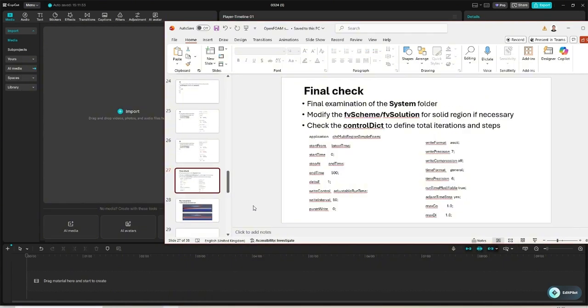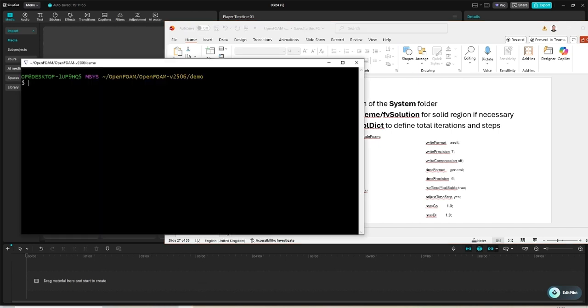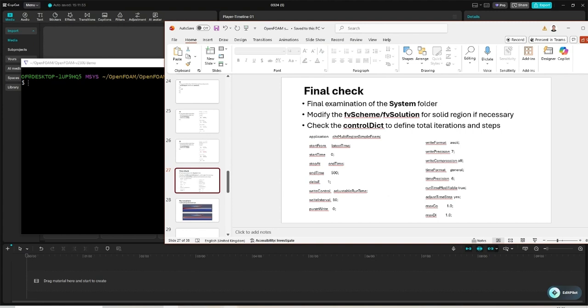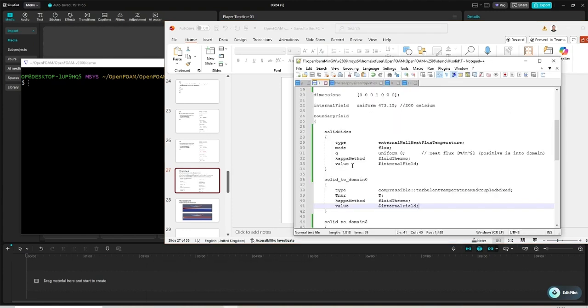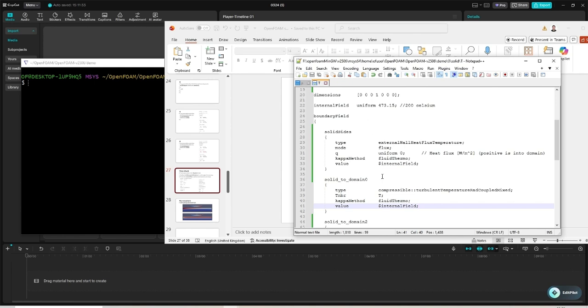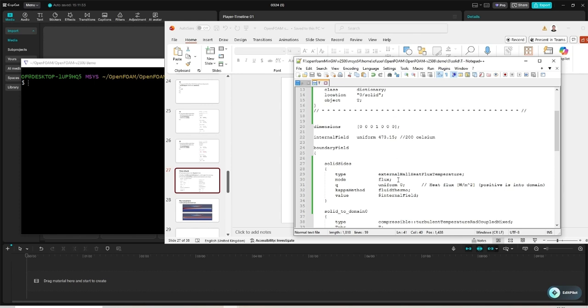So the final solving process is really about debugging all these files we produced according to the warnings. I have another warning, which will give me some errors when I define the solid region's temperature, which means the solid has two sides. These should be insulated. I previously used calculated, but it should be a 0 heat flux at that stage.